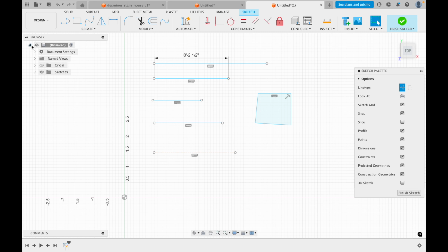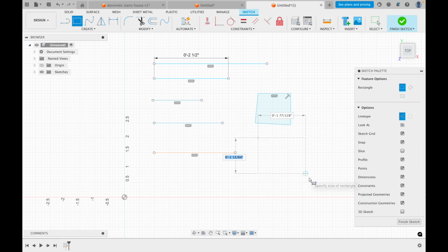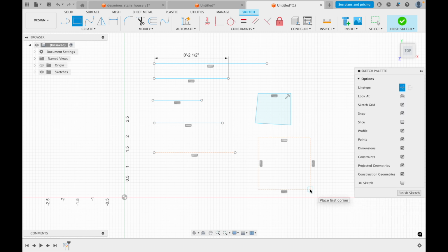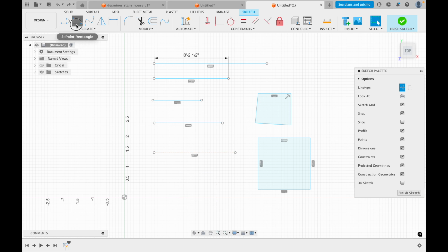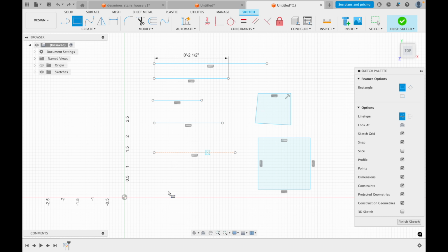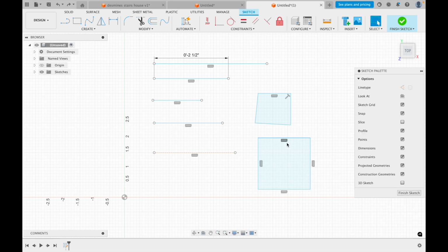So if you want to get, for example, let me make a square for you real quick. And you also need to click out of the construction line if you want to go back to the normal lines, right? Or you can click them both, double click this, and then press the X. But if you want to get out of the construction line, because you will still be in it, you see what I mean? You're gonna have to click that or click a line, and before you try to pull a box or anything, you're gonna click the X, and then you see that disappear, or you can come over here and click that, right? So, this is a reference line, this construction line.